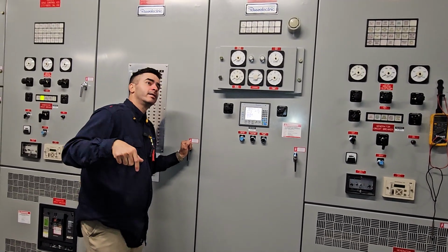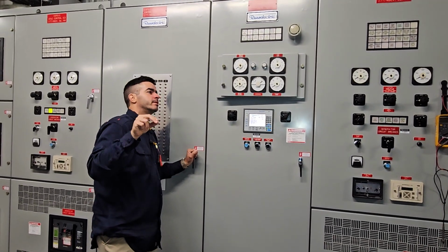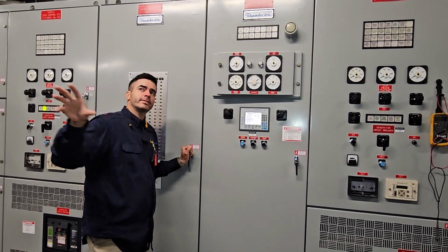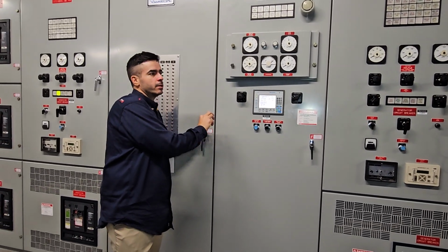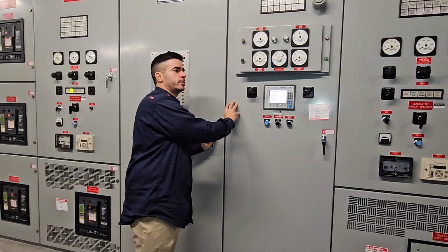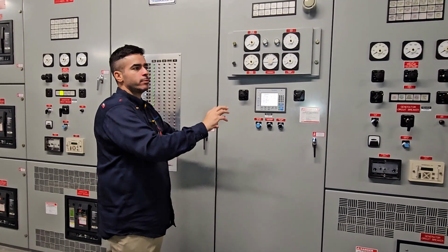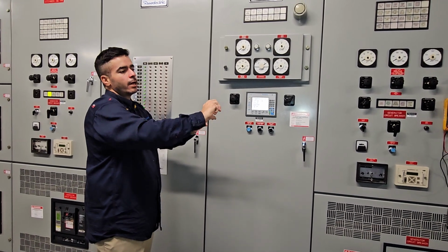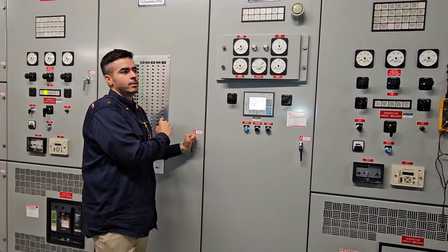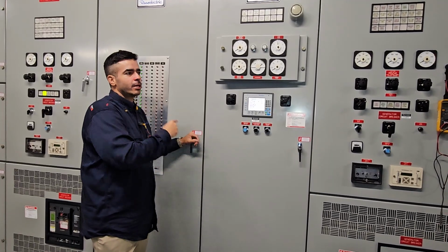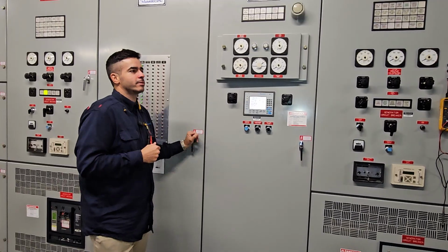Especially this side. Remember the last time I came here, we had an issue where the ATS wasn't reading the voltage. These ATSs look for voltage, but they don't have a direct connection to the bus. They have another electronic device that is sensing the voltage, connected to the bus, and then that one sends it through Modbus communications to the controller. So if you lose that COM loop, then the controller doesn't see it and it just doesn't work.